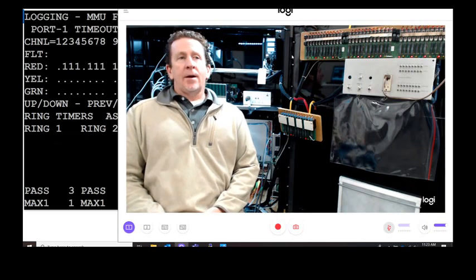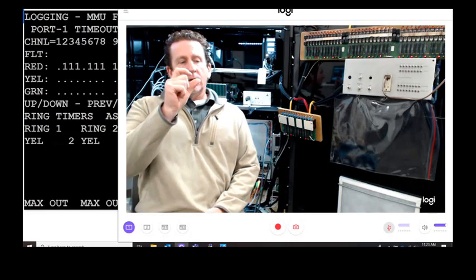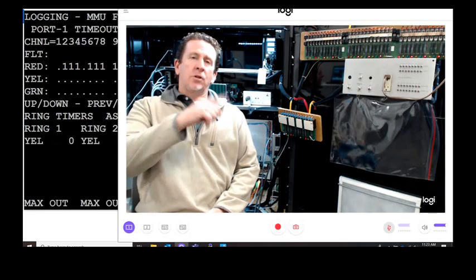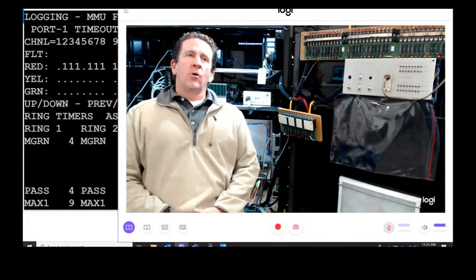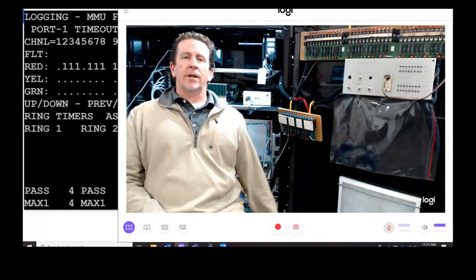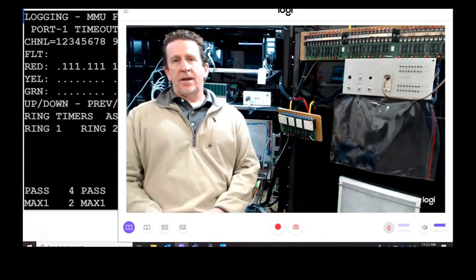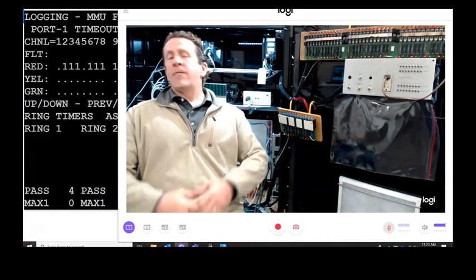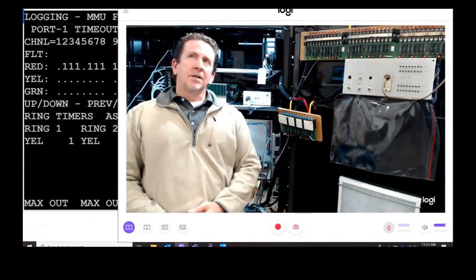So CVM basically gets tied to a lot of other failures. And all the MMU is telling you is that I don't have the voltages up and running, so I have to register a CVM fail. So the CVM fail covers a broad scope of things, but typically that's not what the failure is.